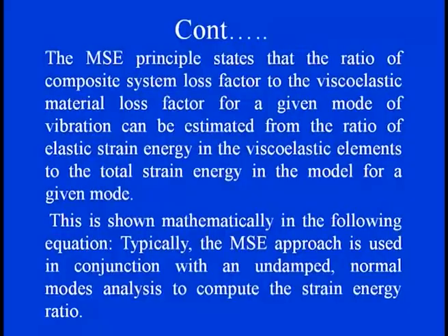This is one of the significant features of this strain energy based principle, that we can straightaway go to the elastic strain energy in any viscoelastic element, and then what the total strain energy is in the entire model. So, when we want to show this mathematically, we need to go with certain equations which consist of the MSE approach in conjunction with the undamped normal mode analysis, which gives you the strain energy ratio.